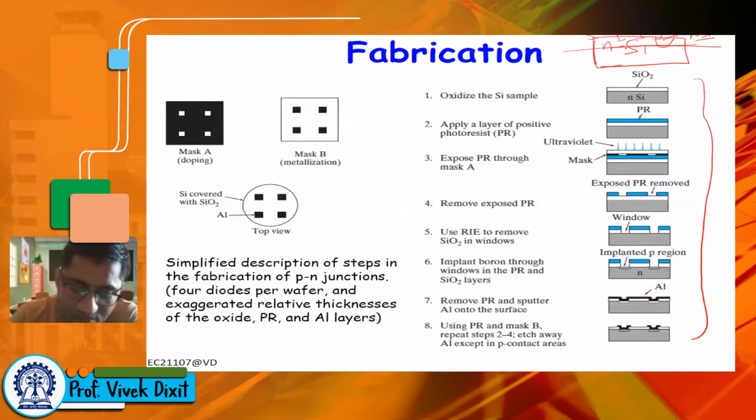let's say this is the top view of the silicon. We want to make a few pockets. Let's say we want to make some n number of diodes. In this example, there are 4 of them. So we will make 4 pockets here where we will make a p-type doping, right? This substrate is n-type, and we choose 4 pockets where we will dope it p-type. So these 4 points will be basically 4 PN junctions, right?